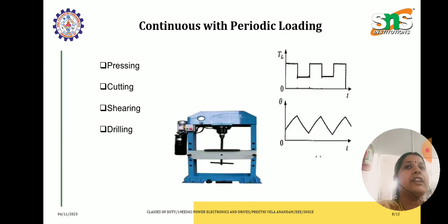And next one is continuous duty with periodic loading. In this type of motor duty, everything is the same as intermittent periodic duty, but there is a no-load running period instead of the rest period. Pressing and cutting are examples of this system.